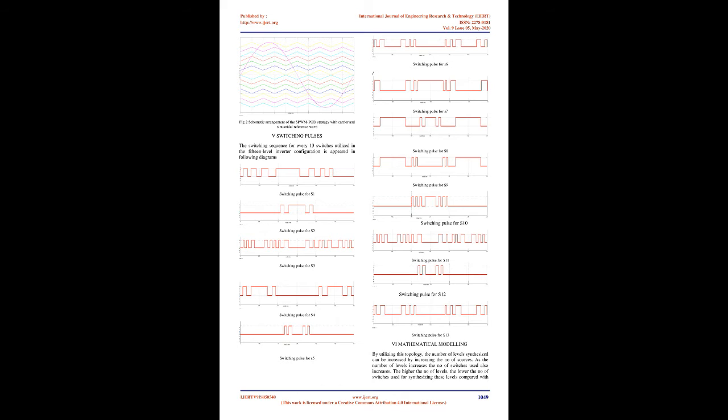The SPWM technique uses several carrier waves and one reference wave per phase. The number of carrier waves used will be N-1, where N is the number of levels. The switching strategy comes under the level shift pulse width modulation technique. The SPWM level shift can be further classified as: 1. Phase disposition, SPWM-PD. 2. Phase opposition and disposition, SPWM-POD. 3. Alternate phase opposition and disposition, SPWM-APOD.